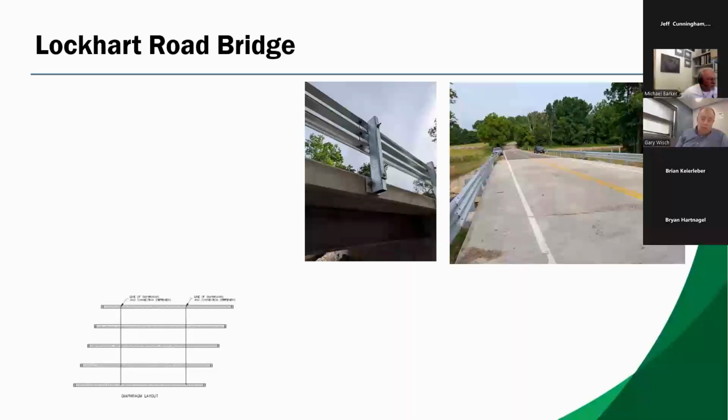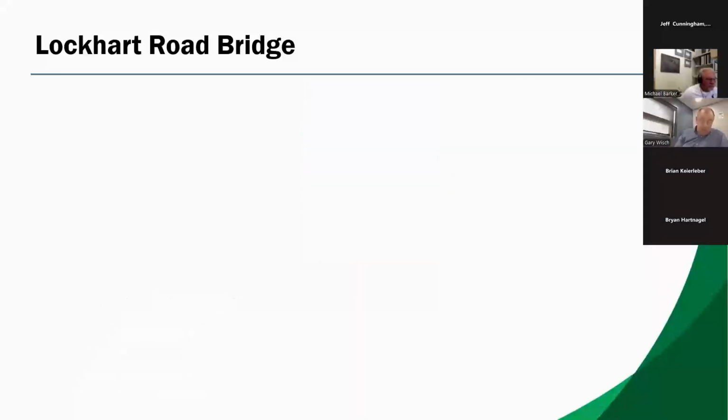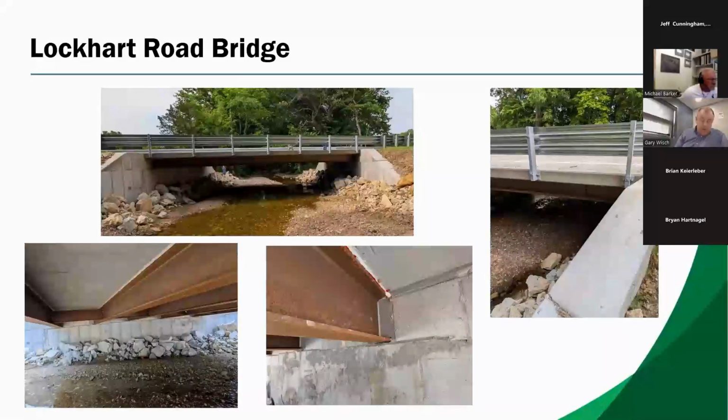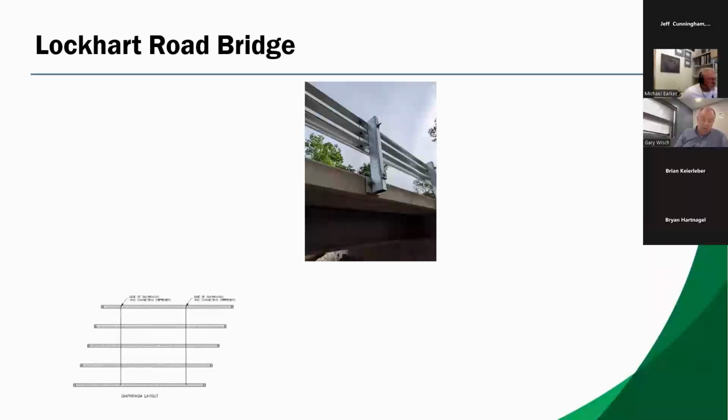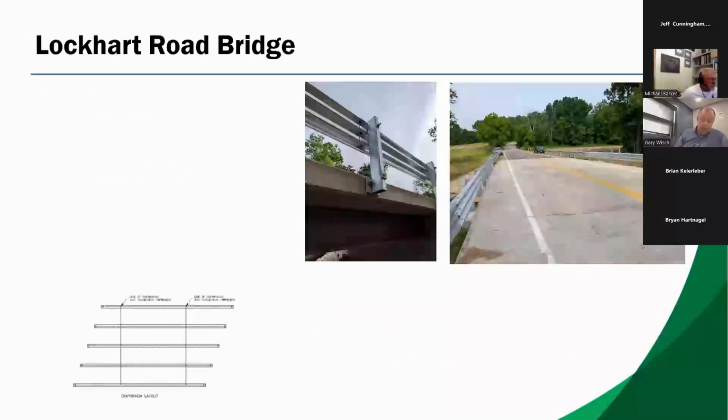We chose a welded diaphragm connection plate on the first bridge, Hendricks Road, because we're more familiar with that. We do that more often. We chose the bolted angle connection to the diaphragm on the second bridge. We decided to try that because in our shop, hole making is a little bit more automated than stiffener welding. And so we felt like we saved a little bit of time with the bolted connection.